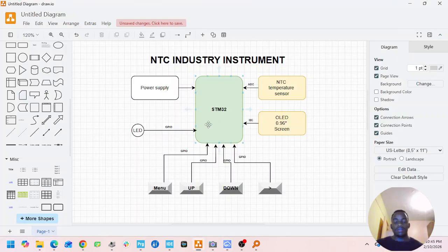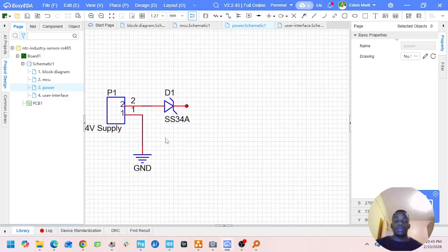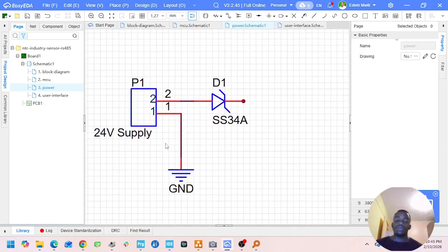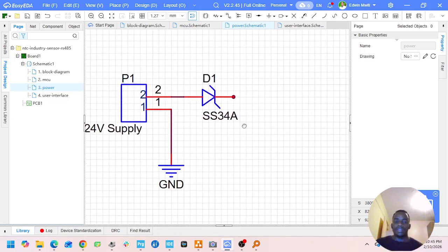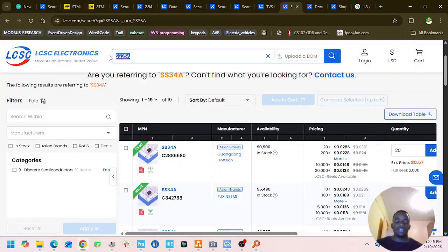So the next thing, the best culprit we can use there is now our switched mode power supply. We cannot use a linear low dropout regulator because of the heat losses. So we'll look for an SMPS, and no other better SMPS to use than the typical LM2596.